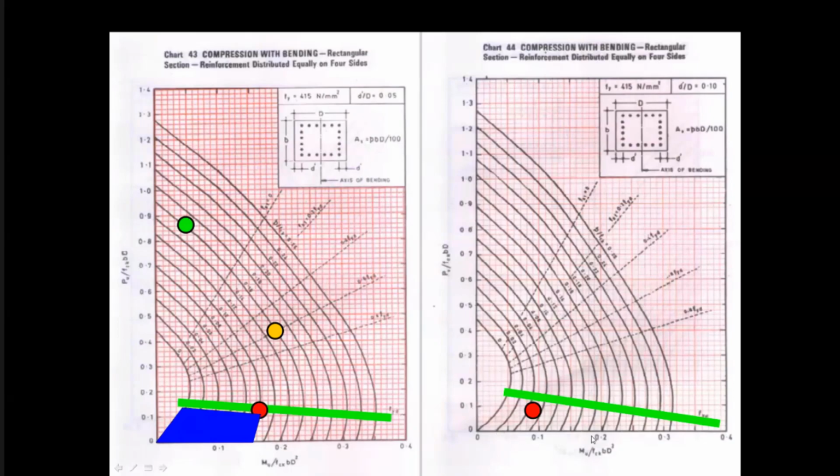Now, if truly you want to make ductile piers and bridges to swing back and forth with yielding of steel, you should stay below the green line. But where are we today? We are sitting on the apex corner here. We're making very small column sizes, and that is why we are going to have great trouble in the design of bridge piers, because we are making them fail in a brittle manner, because we have chosen very small cross-section area.